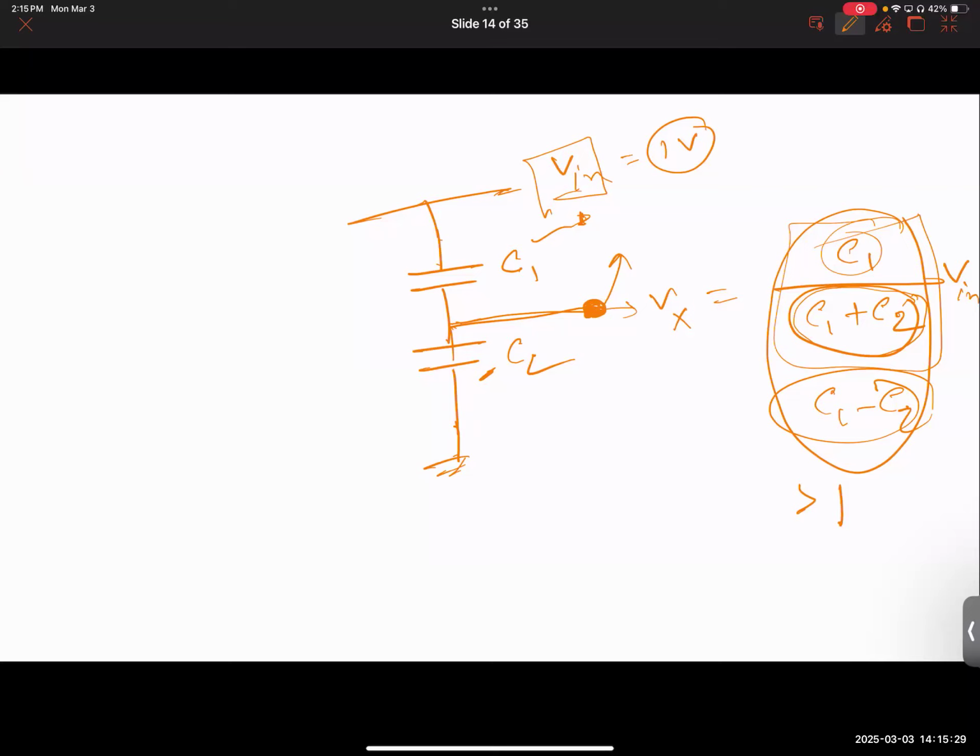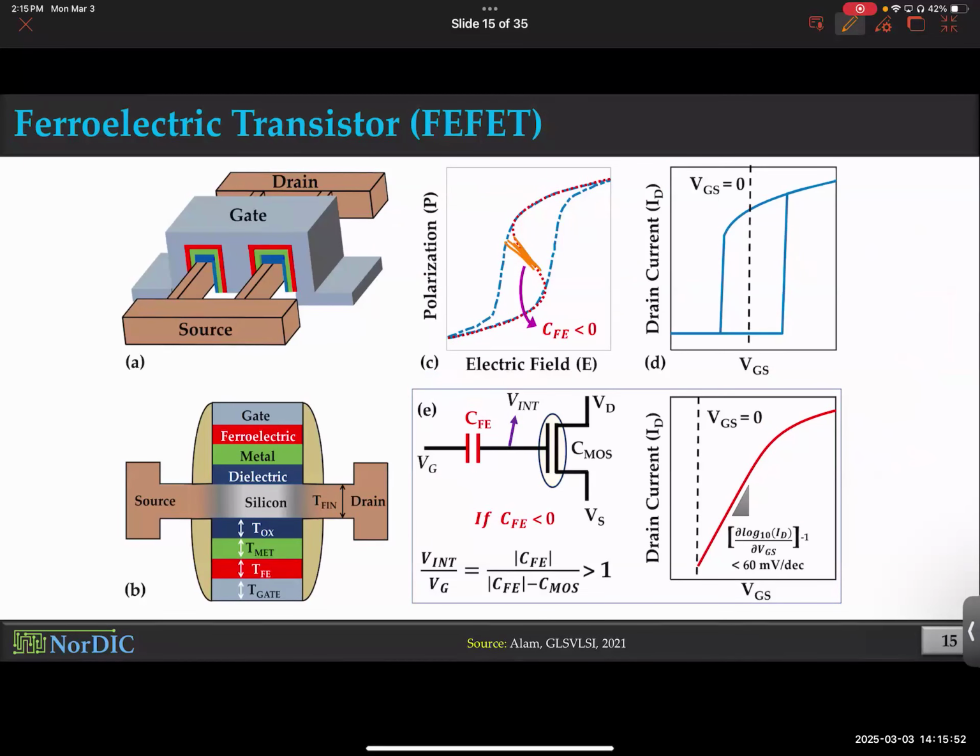But the point is, if you could achieve negative capacitance, wouldn't that be wonderful? The easy way to get the signature of that is to see the amplification of voltage. You haven't used any amplifier, but you apply a voltage and you're getting it amplified internally using the internal energy of the ferroelectric material. That means your electronics could work with much lower voltage. You apply a lower voltage, but the material amplifies it and provides a higher voltage internally. This is crazy, I know. People couldn't fathom where this extra energy is coming from. There are other theories about the domain dynamics of the ferroelectric that give rise to this extra energy. It's a mess.